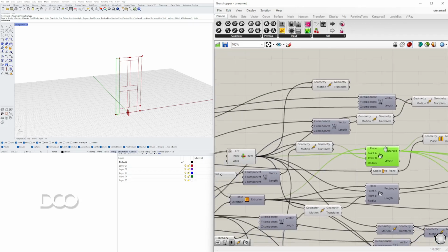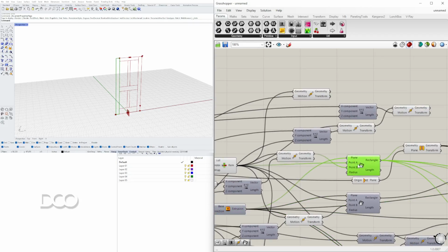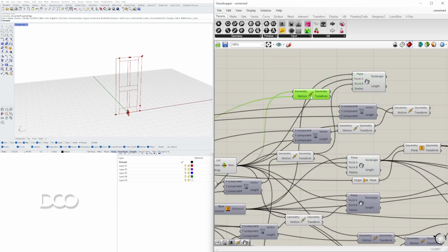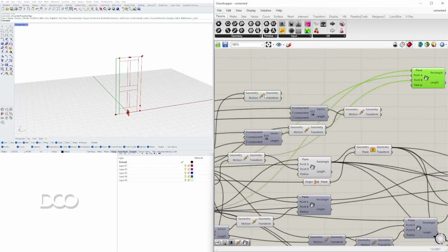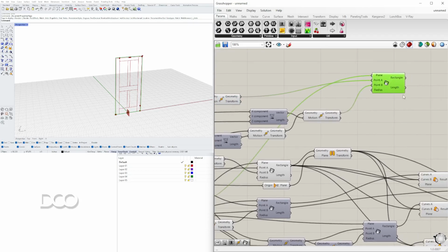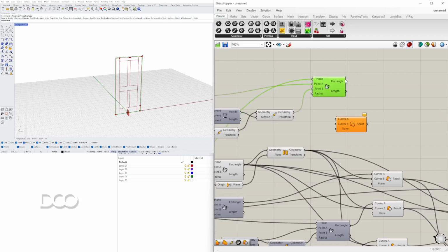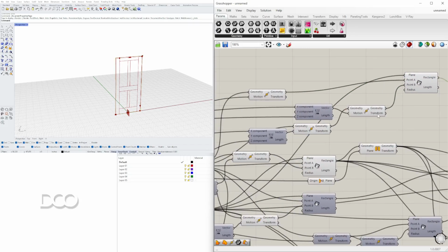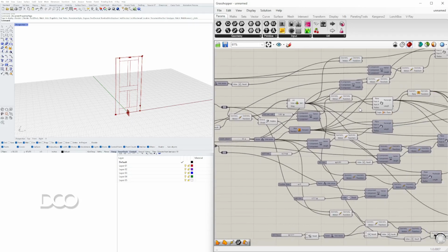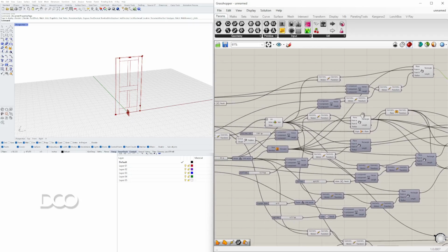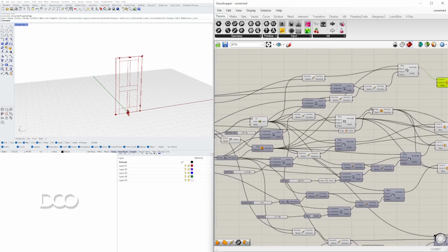And if you know that we need to use this as a reference plane, we can use this copy because it already has everything except for our points. Now we can use our initial point and then point B. Perfect. Now we can do, once again, region difference. So we'll use this rectangle for overall outside, and I choke a little bit because some of these are similar steps, but I think it's so cool when it's done parametrically here.